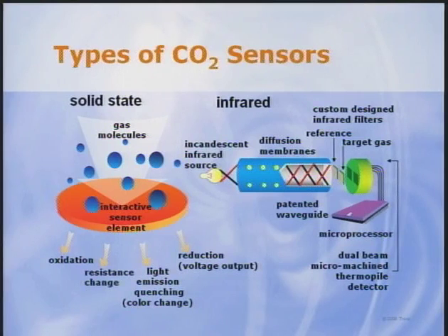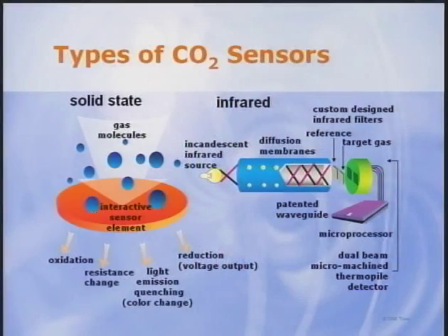There are three commonly used infrared sensors: single beam, dual wavelength, and dual beam single wavelength. The single beam sensors are, of course, less expensive, but more likely to get out of calibration. To keep reasonably calibrated, most use a self-calibration technique that assumes that the space will be unoccupied at night and thus self-adjusts its reading to approach 400 ppm. This logic, of course, will not work if the space is always occupied, like an airport, and if the nighttime infiltration or ventilation is not sufficient to bring the room concentration down to ambient. The dual beam design, shown here, and dual wavelength design are intended to improve long-term calibration, guaranteed by most manufacturers for 5 years or more.